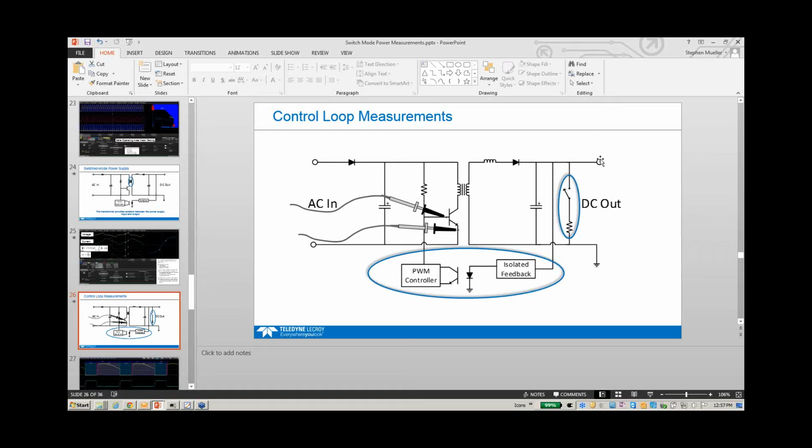In terms of looking at the quality of the caps, I'm not sure if you mean just the quality of the output voltage, but looking at the ripple on the output voltage is going to tell you if you need to add different caps or inductors to filter that more. So I'd really be looking at the ripple measurement to tell me what sort of output filtering I should add.